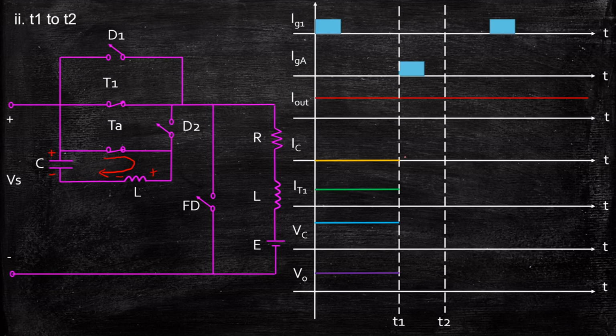So what happens to the nature of IC? IC basically will have a sinusoidal kind of waveform because of the oscillatory nature. Because the energy in the capacitor is going to the inductor, and again the energy in the inductor will go back to the capacitor, and through that it will reverse its polarity. Meaning to say plus is available at this point and minus is available at this point. In the next cycle, once the inductor is completely charged, it does not allow sudden change in current. It will reverse its polarity to plus and minus, and again it will act as an energy source, and the capacitor will charge with a polarity minus and plus in this particular direction. So this keeps repeating. It's basically a sinusoidal pattern that we will observe. As a result, we will have a decreasing capacitor current as the inductor is charging, and again an increasing capacitor current through this particular path. I hope this point is clear.